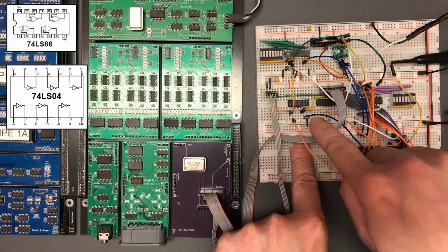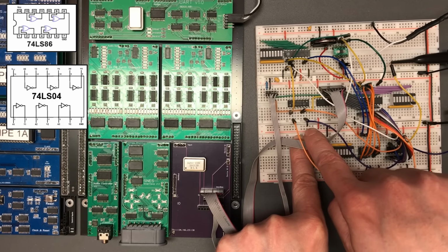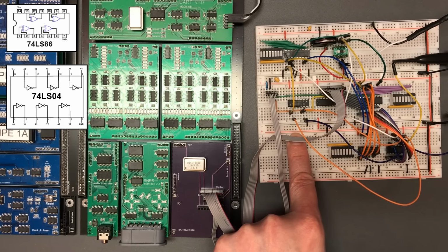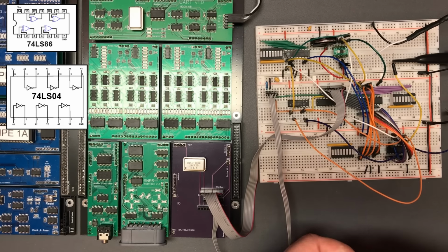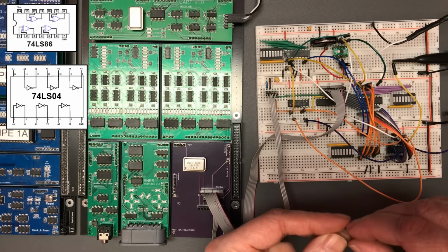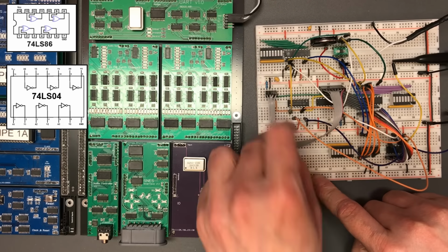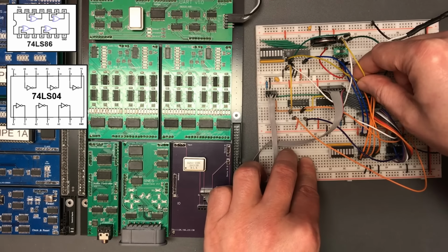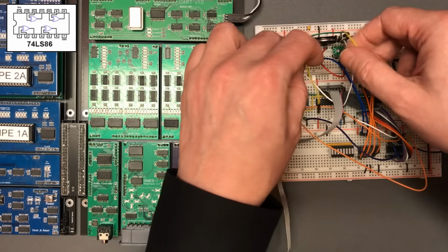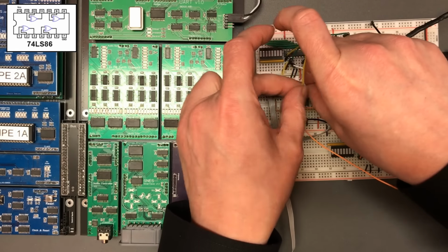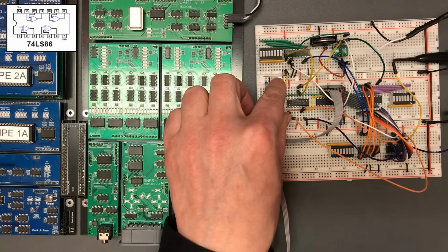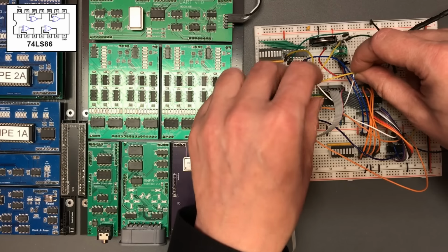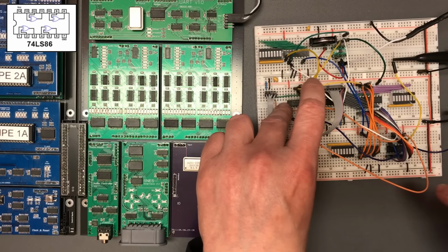So we still want this original one to be a basic inverter. So rather than just a single input and an output, it's got a second input here. So I'm going to pull the first input high to make it always invert that signal. Now I'm going to drop these clock lines that go to the 2 devices. Let's put them on the output from that exclusive OR gate. I'll take the input from the clock line as we use it.